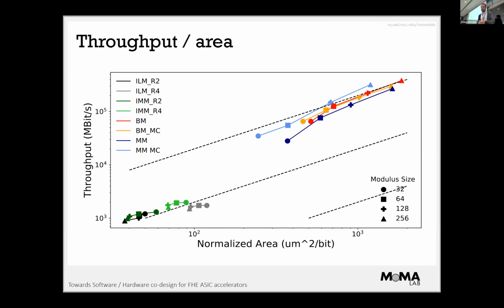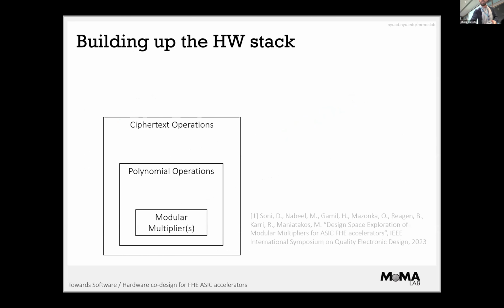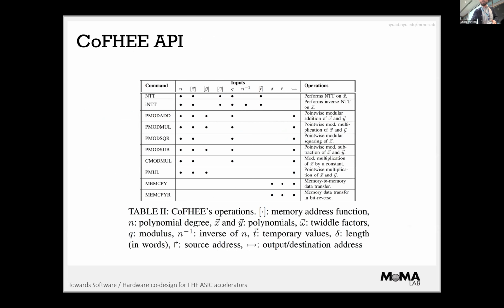And your other question, GPCFG, that's the general purpose configuration registers. They're used to set up things like what is the coefficient size, what is the algorithm for the NTT. We have a few options that need to be set up. That's what the ARM core is actually doing, in order for the chip to work properly. It's like initialization registers, configuration registers.